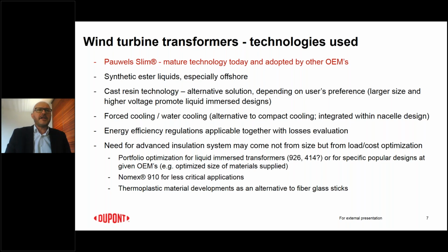Definitely, especially in the last years, the energy efficiency is more and more important for the transformers. So the wind turbine transformers have to meet the requirements for the energy efficiency regulations. Officially, the energy efficiency regulations, at least in Europe, do not apply to the offshore installations. So the offshore transformers would not have to comply with the European regulation.